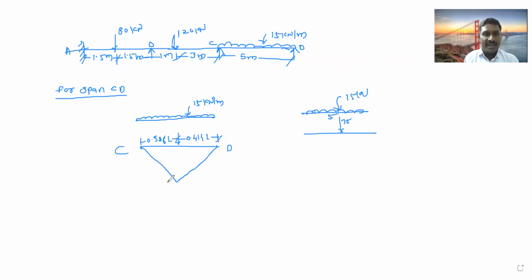So this is the mechanism here, and this is the displacement. Now at point C, tell me, will the moment be present or not? C is which type of support? Continuous. Good. So here a hinge will be there, MP will be there, and the rotation will be theta here.